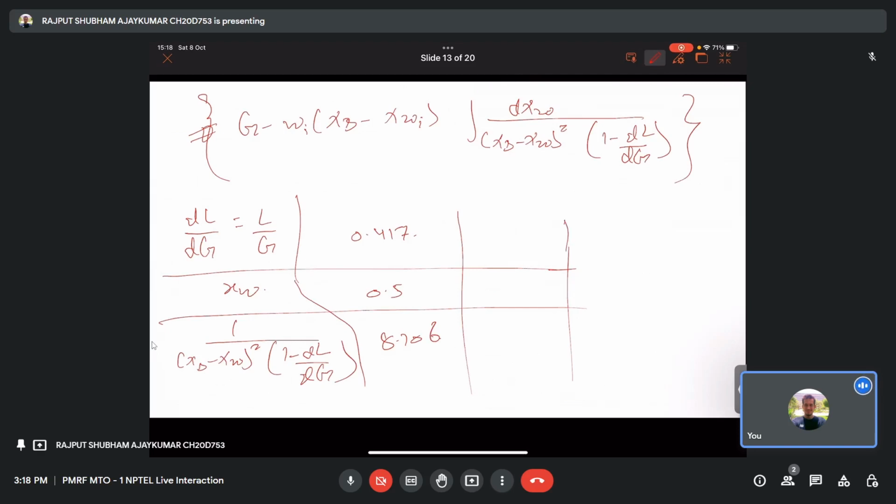Suppose another value, I will just write it out. These values I'm getting after solving the above equation. Okay, so what you have to do is, using the xd and xw data from the plots and using the slopes of the bunch of operating lines drawn, evaluate the integral of the following equation. So we have to evaluate the integral of the following equation either numerically or graphically to get the total number of moles of vapor generated during the distillation. So this is what you have to do here.